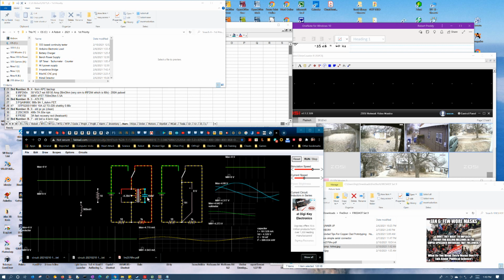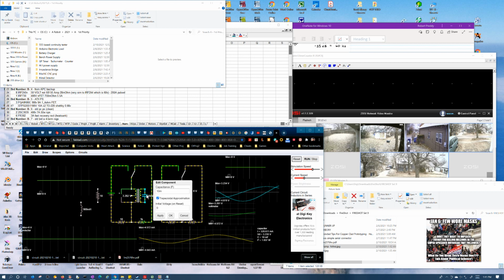Okay, but just realize that it's going to fluctuate, but it's only 5 volts. We're only getting plus or minus 5 volts roughly on these oscillations. But again, that has a lot to do with this being such a big capacitor. But rather than sit here and wait for it to run out of juice, I'll switch it back to what it originally was, which was 10 microfarad.